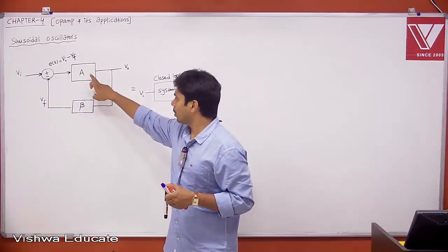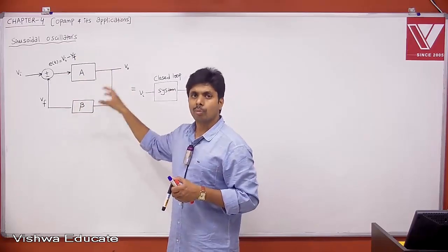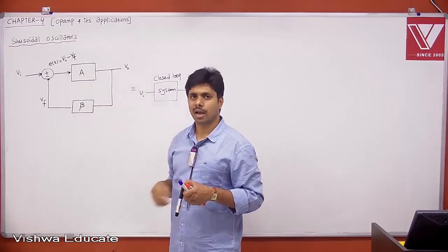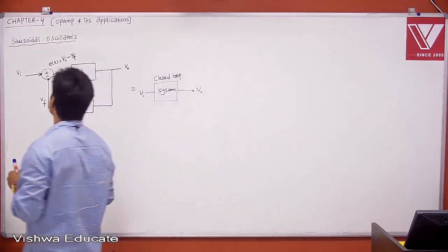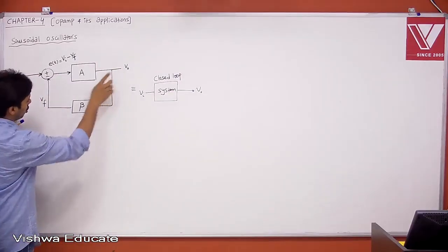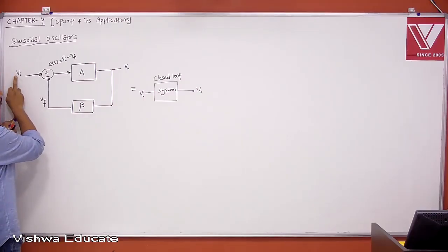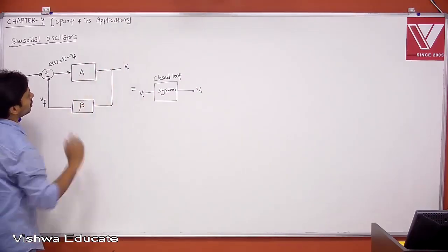Even though it is having open loop gain and feedback network beta, we can convert it into an open loop system with unity gain feedback. I already told, right? If I'm looking for system stability, if I say the signal is bounded here, surely this is also bounded. Definitely the input is bounded, because only for bounded input we are checking whether the output is bounded or not.